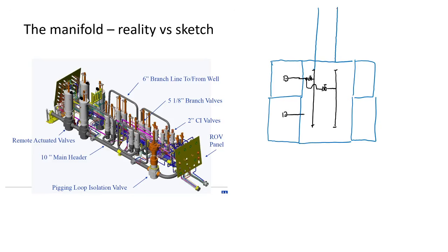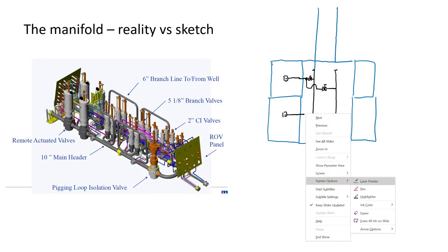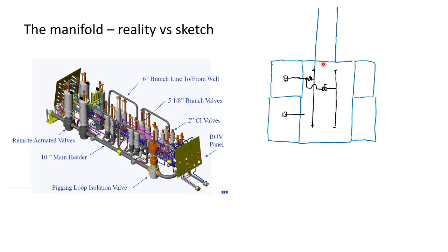You want to have just one point because at some point you want to be able to disconnect this connector. If you need to do maintenance on this module, you need to be able to disconnect the whole module. So it's not good if this split is here, because then you will have two points of transfer, and it will be more expensive. It's better to have just one.